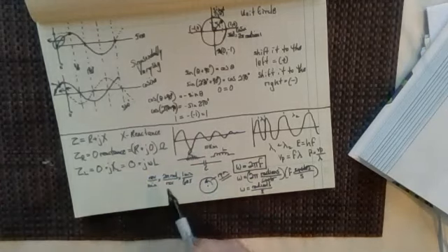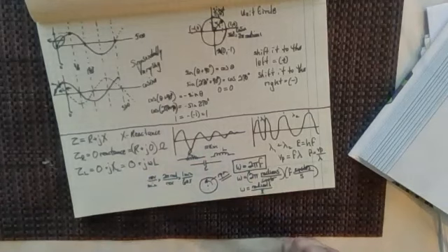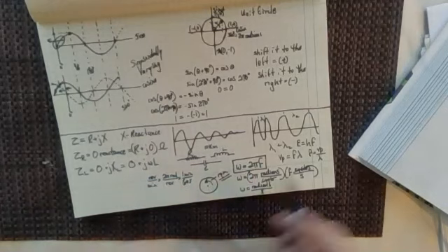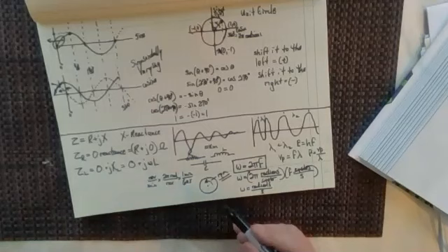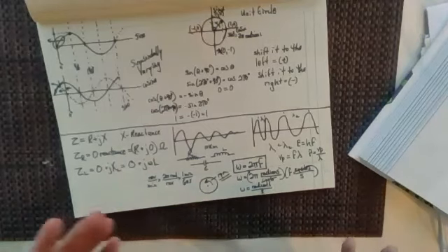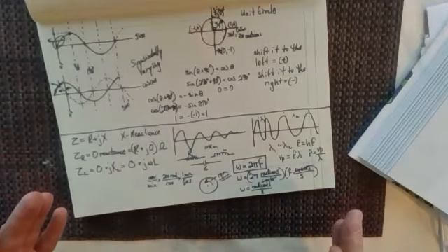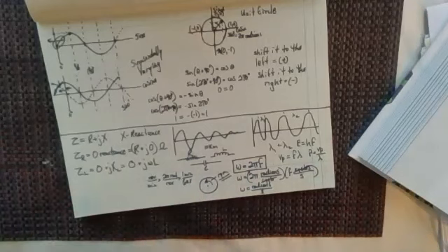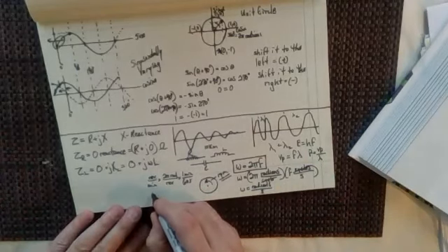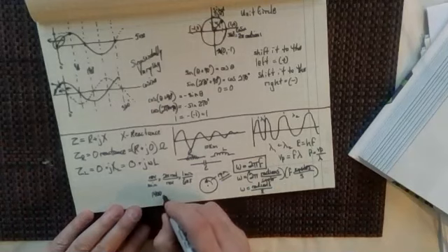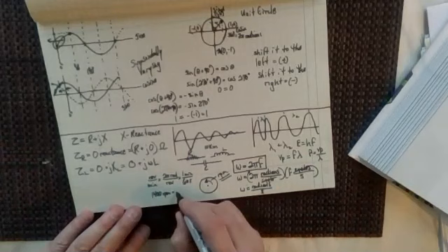And you can almost see the 2 pi radians is 6.28, isn't it? And 60 is about 10 times that. So really, we're going to be dividing this by 10. That's a good rule of thumb. If you ever have revolutions per minute and you want to convert them into radians per second, you're going to end up dividing by 10 approximately. Now, I think that 1,400 revolutions per minute equals